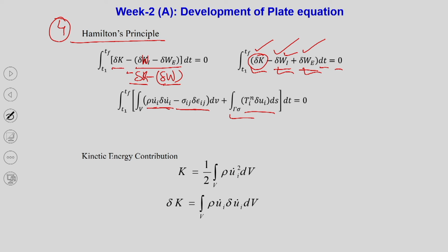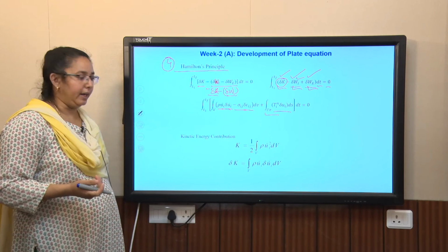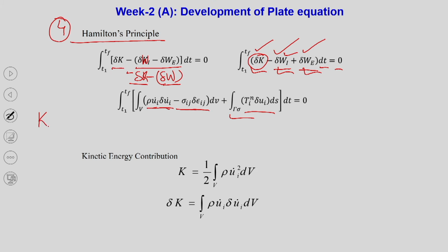So, actually if you talk about a discrete body, your kinetic energy is nothing but half of mv square. I have also discussed these things again. So, for a continuous system, if mass is distributed over a volume, then instead of this we will put half, ρ dV over that volume, that will become the mass, and u is a displacement and u dot. When we have a spatial differentiation, we put the comma, that is u comma x.